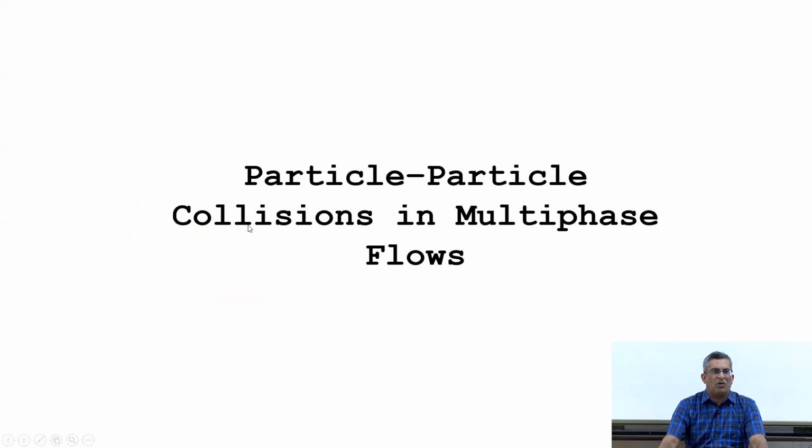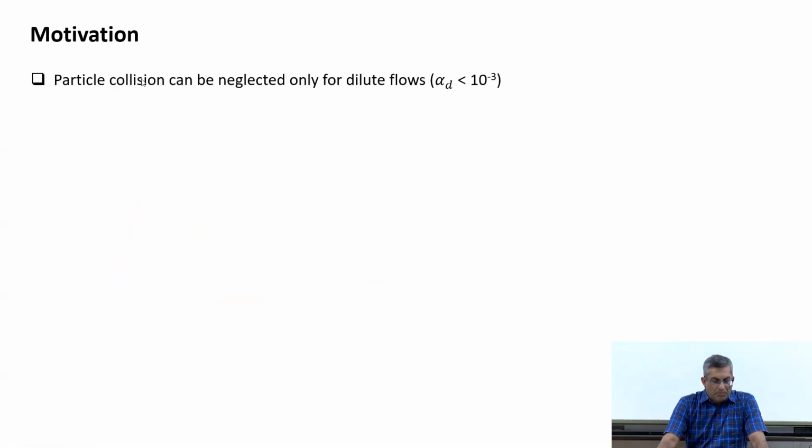So, as of now, we have always avoided particle collision because obviously it brings in more complexity. However, it is important to understand particle collisions in multiphase flows, mainly because we can neglect particle collisions only when we have dilute flows, typically if the particle volume fraction is less than 10 to the power of minus 3.